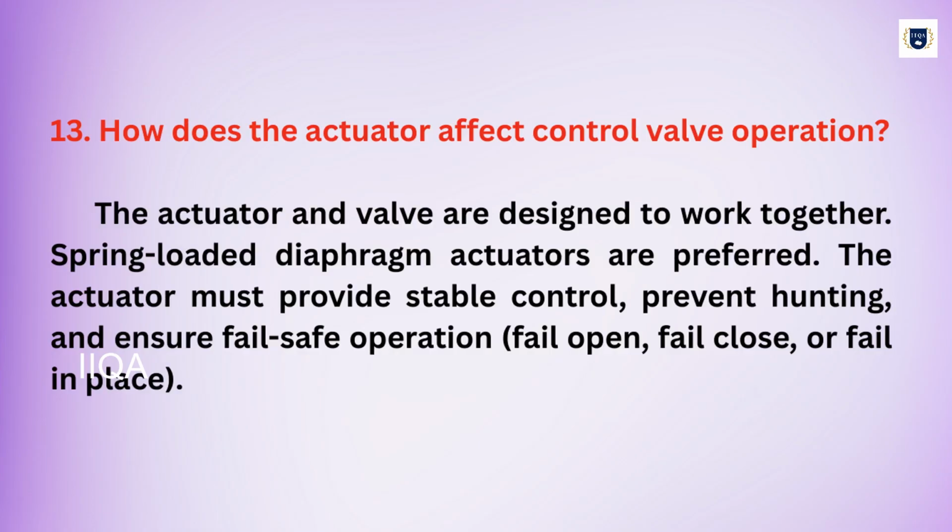How does the actuator affect control valve operation? The actuator and valve are designed to work together. Spring-loaded diaphragm actuators are preferred. The actuator must provide stable control, prevent hunting, and ensure fail-safe operation: fail open, fail close, or fail in place.